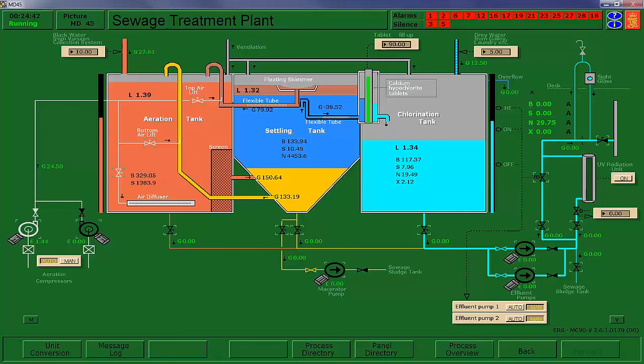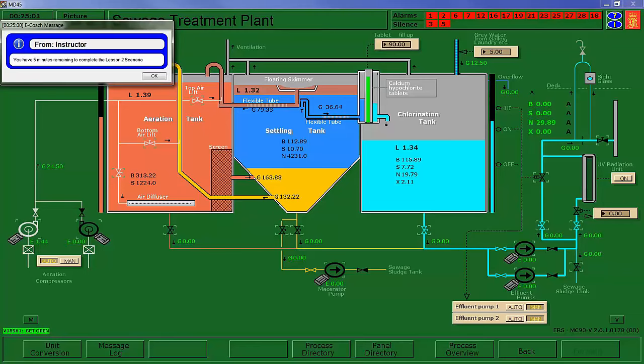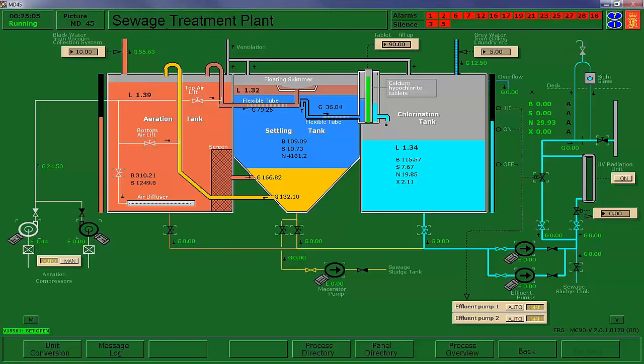So then we'll open up the suction from the aeration, the chlorination tank. We need to open up this bypass, and this is electronically controlled as when we put this in automatic. Then we'll go ahead and open the pump discharge. We have 5 minutes to complete the scenario. Set this at about 40% rate. We'll put the overboard open,